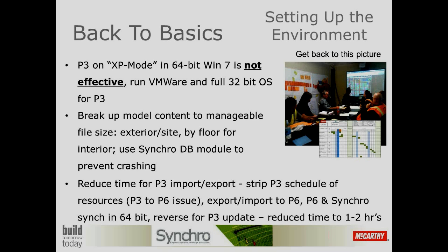The other thing we've had to do is break up the model content into manageable file sizes. It doesn't like 150 megabyte files on some of the files. So we've broken them down into the distinct groups for planning purposes, for the interiors, exterior site, those kind of different things. Breaking those down, but bringing in the entire schedule, while limiting the scope of the 3D content that was in there.